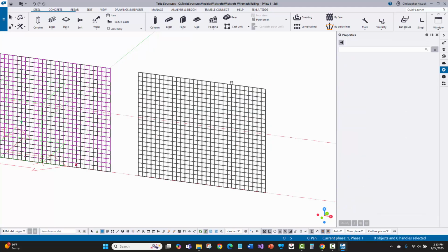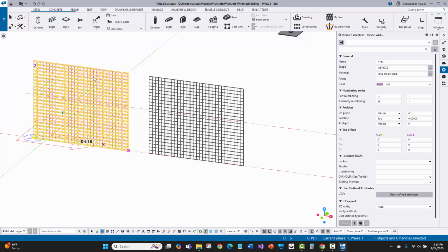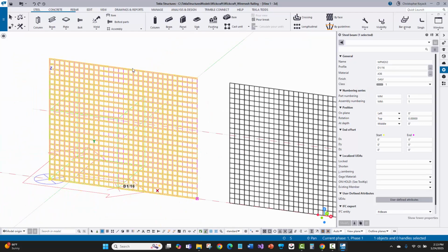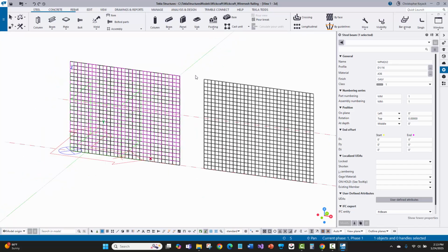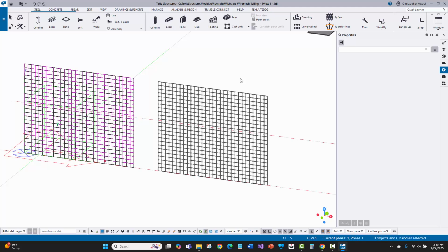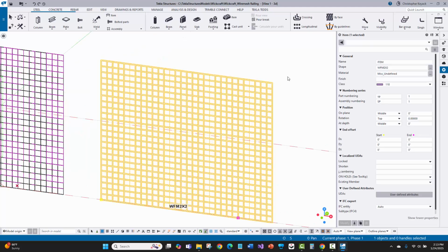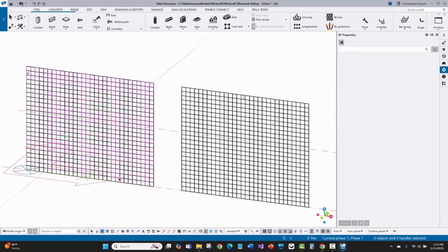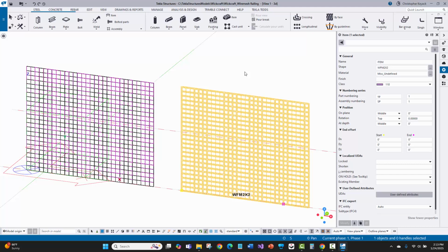The other thing that's nice about this is it's much lighter weight than this part add over here on the left. Like even when I have it selected and I try to zoom in a little bit, my computer has to jump a little because it's got a lot more objects selected than say this lighter weight one. And items were intentionally designed to be sort of bought out items and things that don't really change in geometry or shape that much. Things like brackets or maybe even a standard mesh panel or grating treads for stairs and things like that. So the item route is another great way, especially if you want to keep your model a little bit lighter weight.